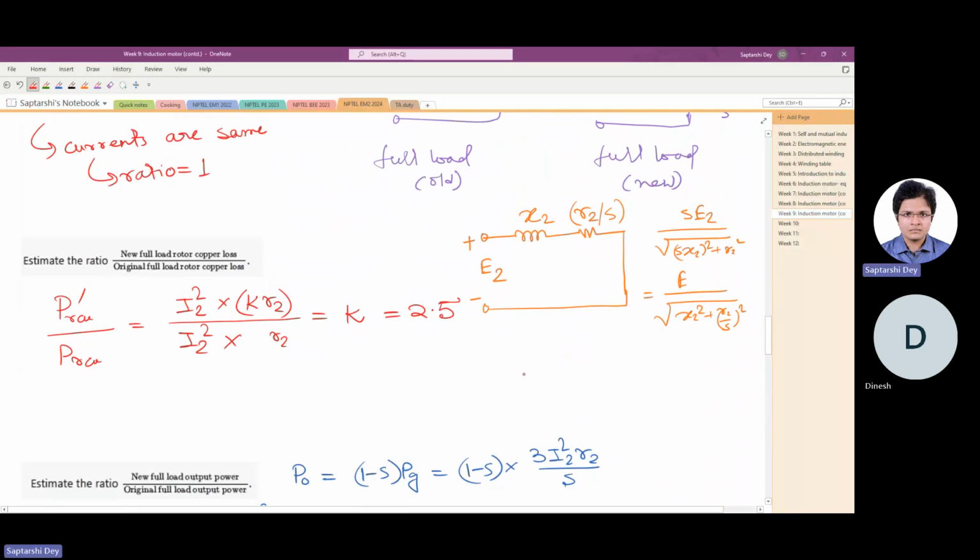We had this discussion, right, that different frequency sources cannot have non-zero average power supply in between them, right? So if we do this, we can conveniently draw the induction motor equivalent circuit like this. That's why we did this jugglery, so that this rotor circuit becomes frequency independent.